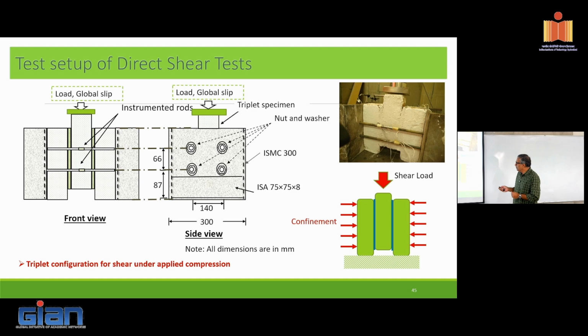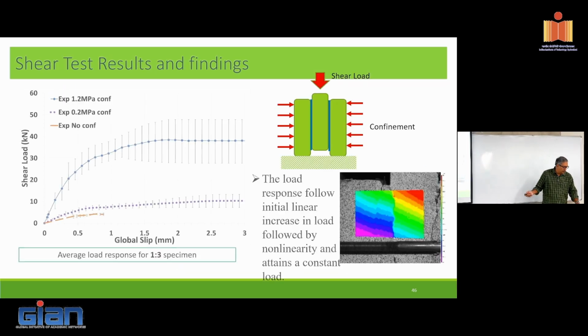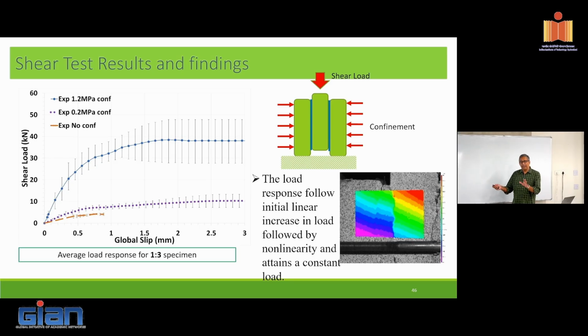So you could do something like a triplet test, which is typically done for masonry, to understand the stress transfer happening across this interface here, right? And you could actually come up with, we've done a lot of work in masonry, where we looked at shear transfer across this joint here. Of course, now I've switched gears, I'm talking about masonry.